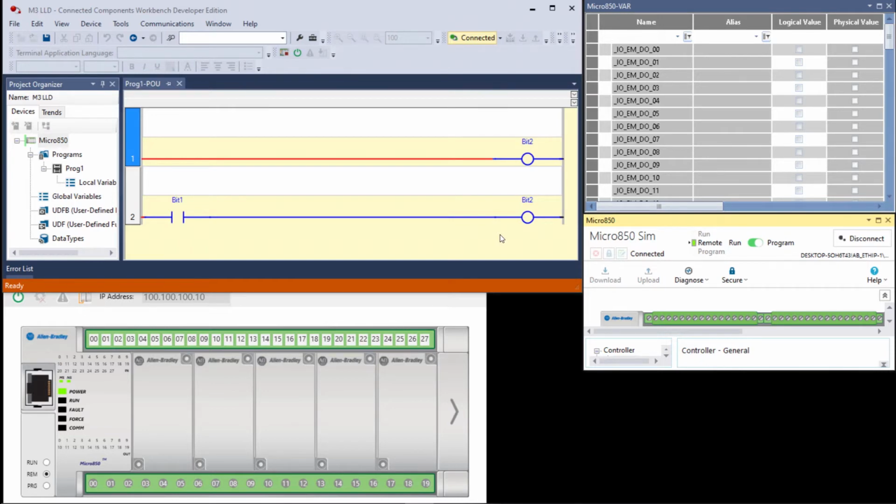And that's something we need to emphasize now that we're talking about ladder logic diagrams and we've gone beyond one rung. We have 2 rungs here, both of them addressing bit 2. The first one would say, hey bit 2, you're on. The second one, because it's false, would say, hey bit 2, you're off. But we're in the program mode. But again, this is exactly how it would look if we went to the run mode.